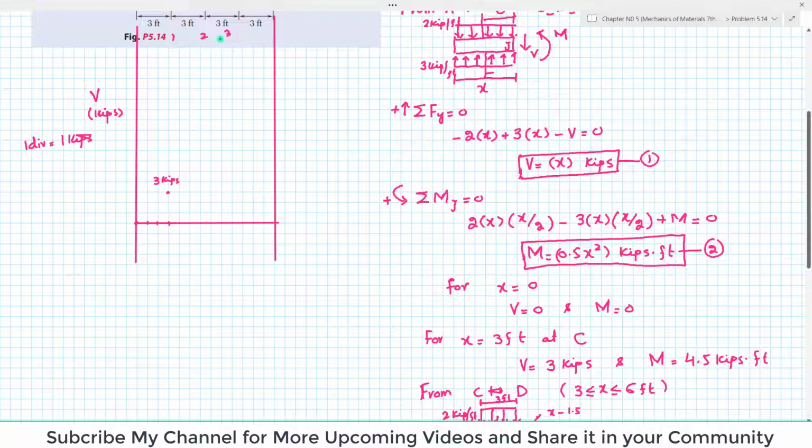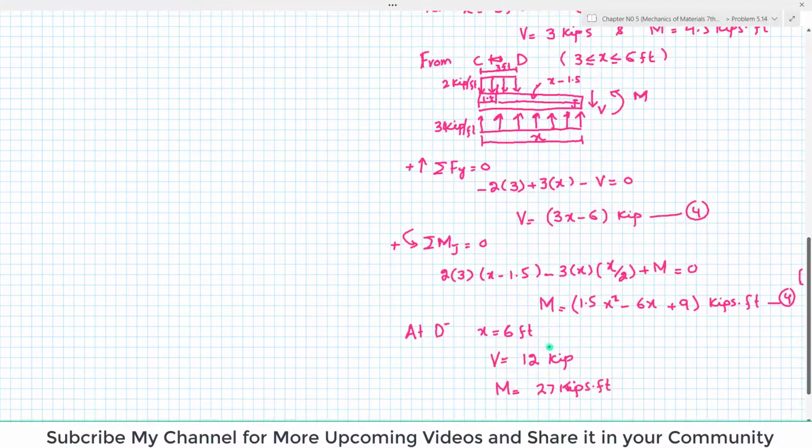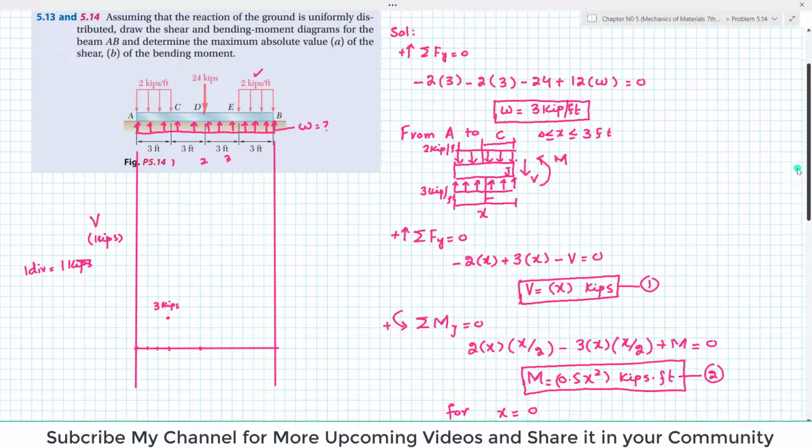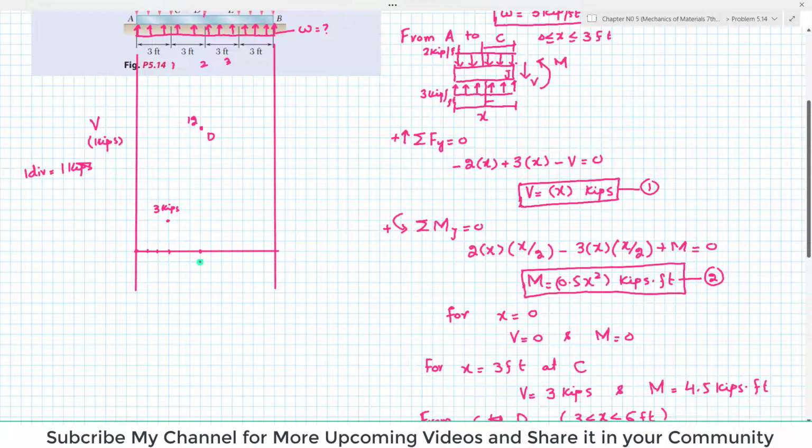Clear? Similarly, at x is equal to 6, at this point D, we have V is equal to 12. So we will plot 12. So 3, 4, 5, 6, 7, 8, 9, 10, 11, 12. So this is 12. But again at point D, you can see that there is 24 kips downward. So 12 minus 24 will change the shear force to minus 12. So 1, 2, 3, 4, 5, 6, 7, 8, 9, 10, 11, 12. So it will be minus 12.